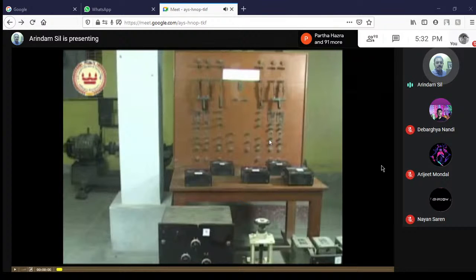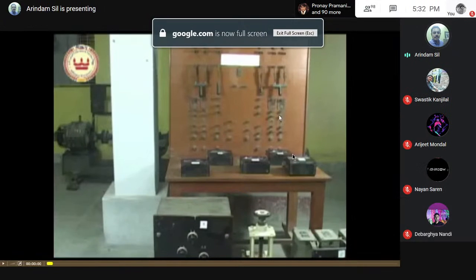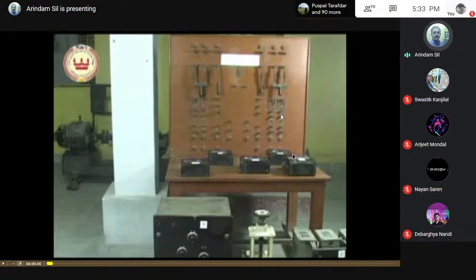Just now one girl was telling us, the voltmeter is in parallel, so the voltmeters can be connected out here, right? What you do is you have the source voltage voltmeter connected across here, and another ammeter which is supposed to be connected in series. So that can be done here: if we open a fuse wire, we can connect the ammeter out here. Because my circuit has two fuse wires, I can open one fuse wire, open the terminals, clean them, and connect the ammeter here. Therefore if anything goes wrong in the entire circuit, this fuse will blow off. Clear?